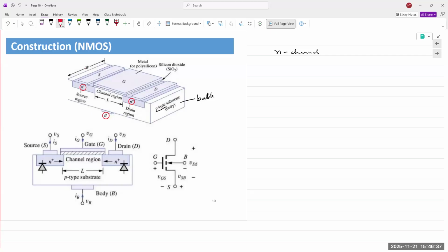In a JFET, the channel already existed. It was a depletion mode device because we had to apply a voltage to turn the device off. We had to kill the channel in order to turn it off. This is known as an enhancement mode MOSFET because a channel must be created. It does not already exist. There are also depletion mode MOSFETs where a channel already exists from the manufacturer and we apply a voltage to turn it off. This one is the enhancement mode. Far more common.